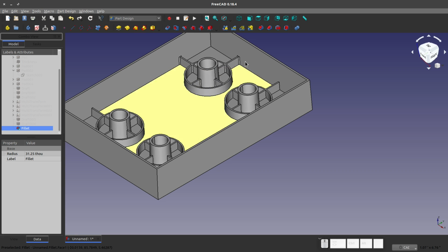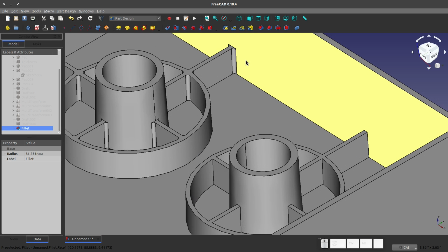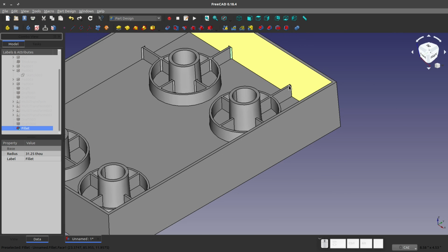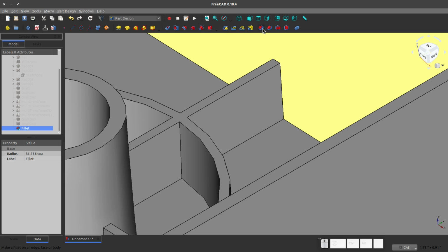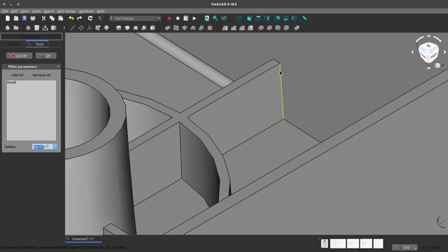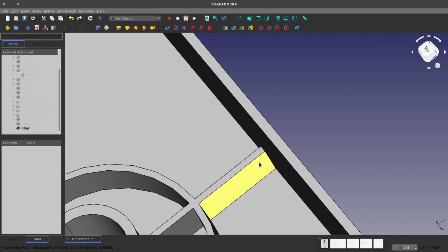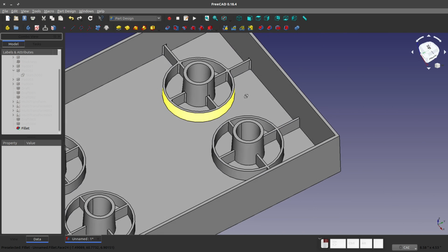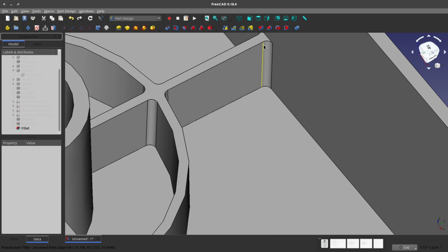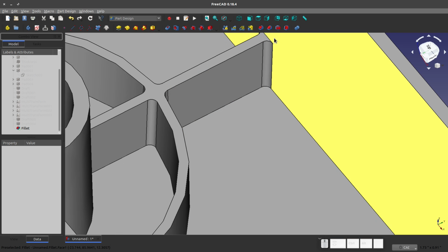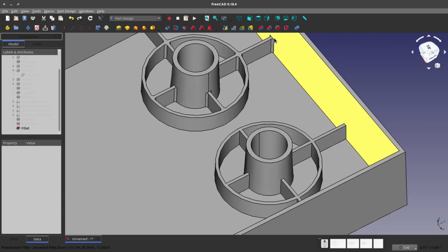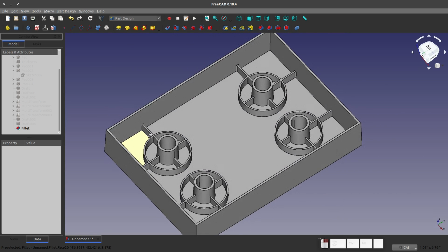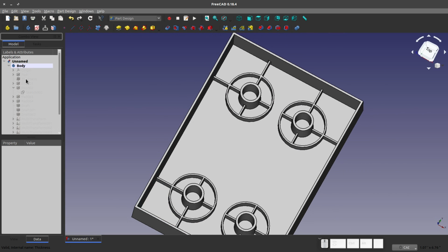Okay, so you'll see here that I've run into a little bit of a problem. This is filleting just fine over here, and this is not filleting okay over here. Well, what I'm seeing is there's a gap. So what has happened is, as we applied the draft feature, it pulled this rib over to continue the rib as it should have. But since I patterned the original feature, that did not work. So I need to make a quick edit.